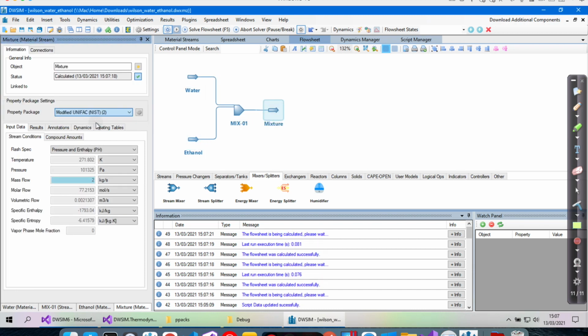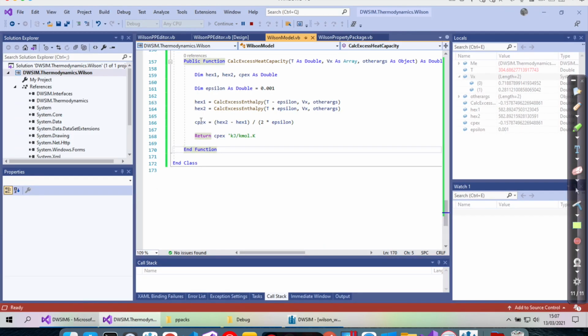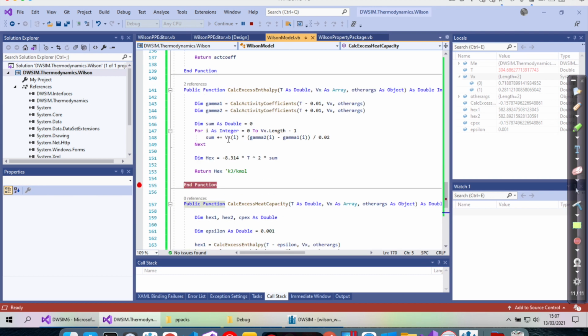Let's say that you are not modeling the heat, but still you can see it from the equilibrium. You can see that we are calculating the heat of mixing from the activity coefficients, right? We are using the values to calculate heat of mixing. If you look at the papers for the modified UNIFAC, for instance, they explicitly say that the original UNIFAC method was not created to represent heat of mixing because they didn't fit the parameters using data from mixing effects.